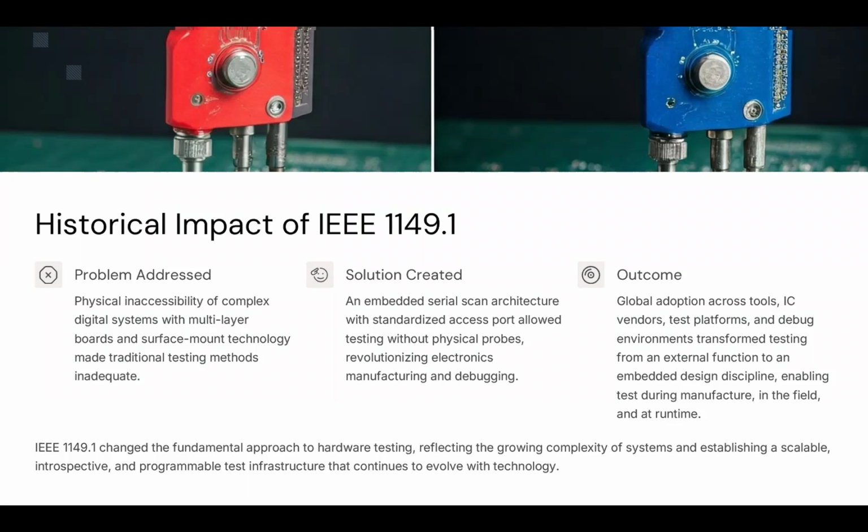Okay, so the test access port, which we call the TAP, is one of the modules, one of the concepts within JTAG testing, and acts like a gateway for external equipment to inject their test data, the test vectors, and read the output. Capture the values, evaluate the pattern, and based on that, detect the problems, the faults, and debug the system.